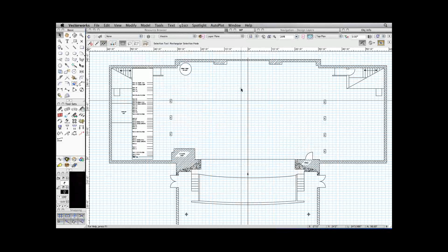At the end of the day, at the end of the process, we'd slap a clean sheet of vellum down on top of that and then trace up to that top sheet of vellum everything that we want to keep, and it's that top sheet of vellum that we grab off the board and run over to the blue line machine and feed through the blue line machine.